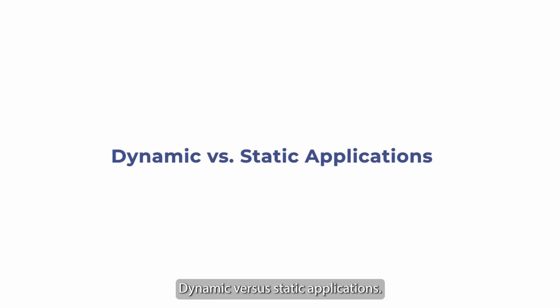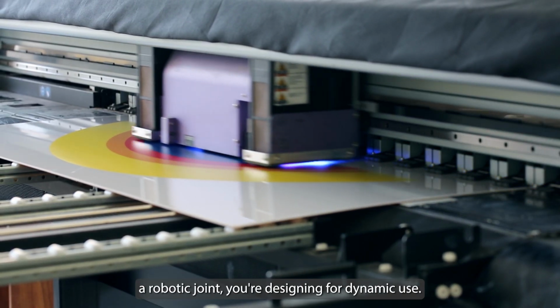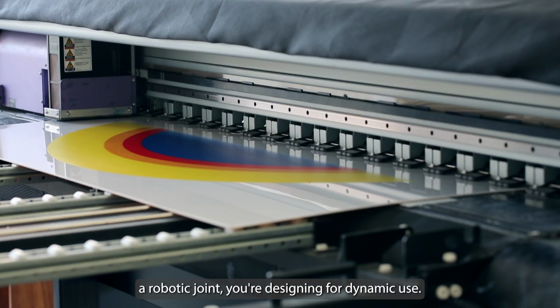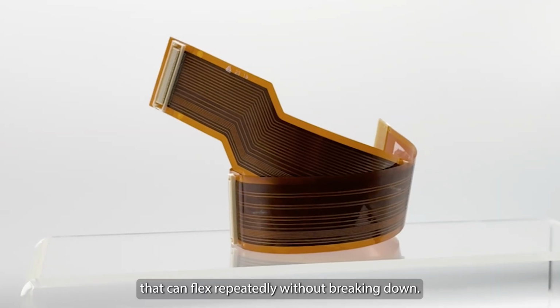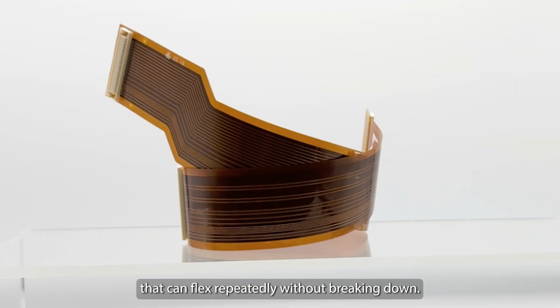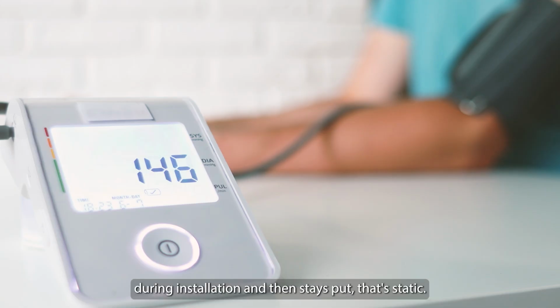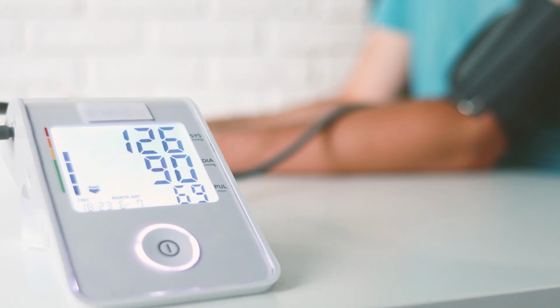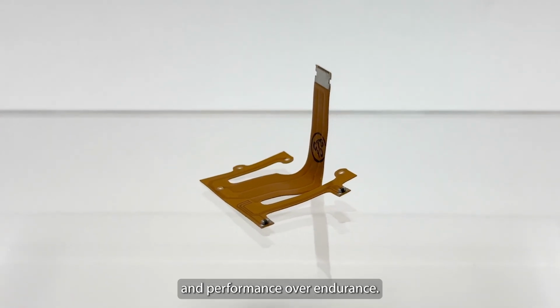Let's start with something fundamental: dynamic versus static applications. If your circuit is in constant motion, like inside a robotic joint, you're designing for dynamic use. That means you'll need materials and layouts that can flex repeatedly without breaking down. But if your circuit only flexes a couple times during installation and then stays put, that's static. In those cases, you can focus more on compactness and performance over endurance.